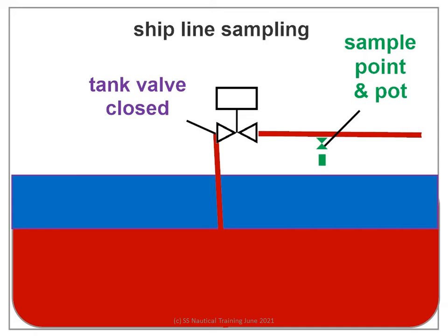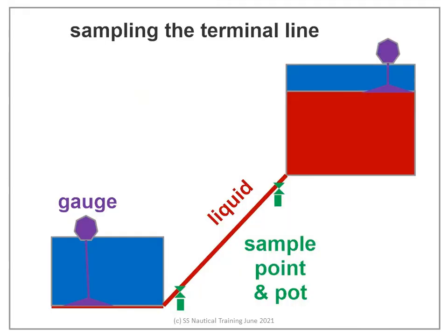The receiver does not want the cargo in the tank to fail because of dirty cargo lines. And even in the event of cargo failure, we need to be sure that it was not because of cargo lines. We take the sample from near the point where cargo enters into the tank, before opening the tank valve. The long terminal cargo line has several strategic points for sampling.